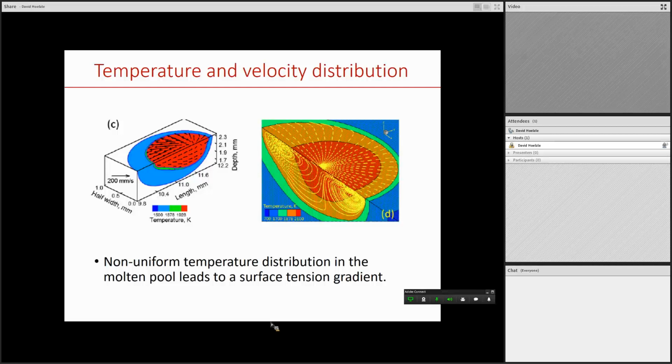And then on the flip side, there are some simulation packages that try to strip away as much of what they call irrelevant physics as possible, and those definitely do not include the idea that you have powder. I'm going to get to that probably not until Tuesday: whether or not you have to consider, or do you have, appreciable heat conduction into unfused powder or not? Is that part of the equation? And then they can strip away a lot of other things too.